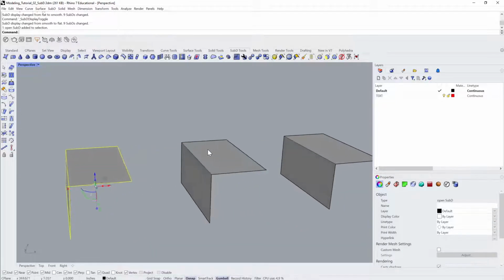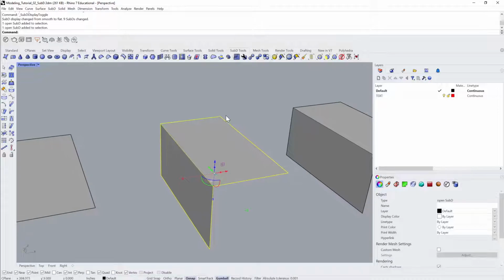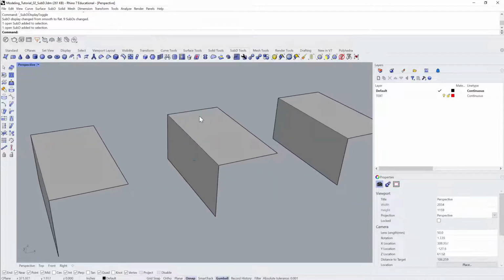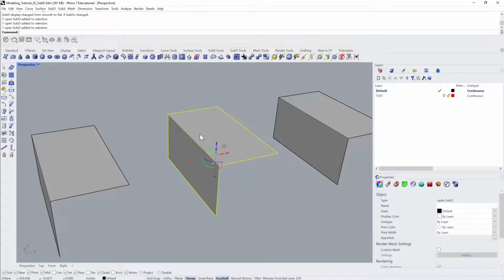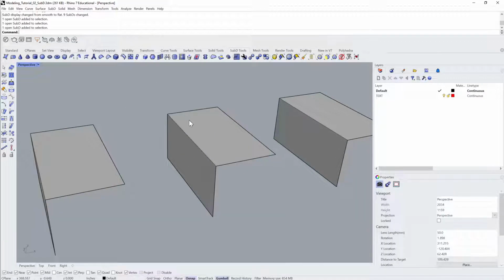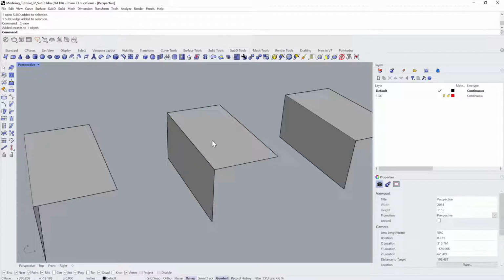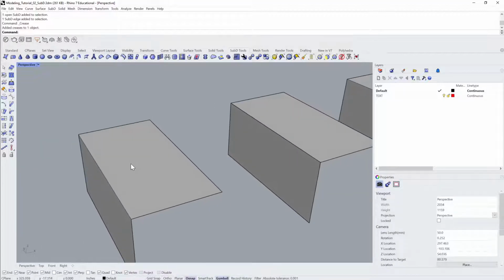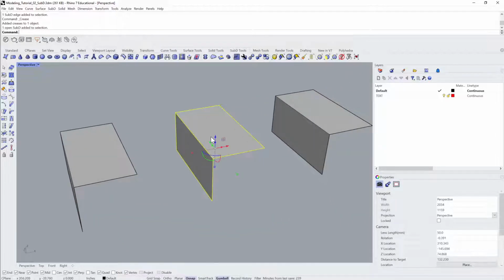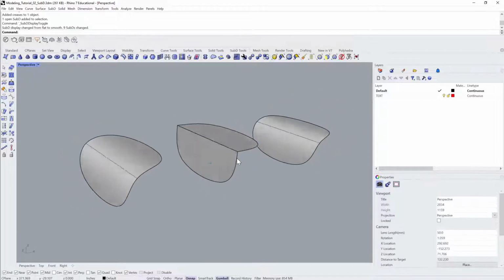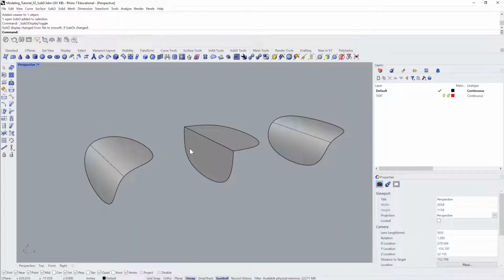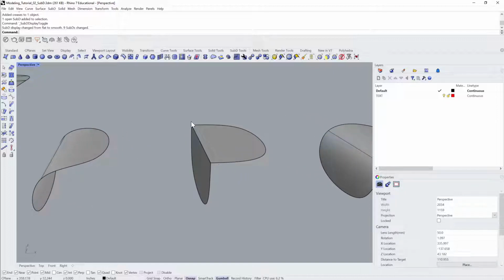and you can see that there's a very rounded transition when I hit the Tab key. Now, if I want there to be a sharper transition here, I can do a couple of things. One is I could add a crease, but then if I add a crease along this edge, so let me just Shift-Control that and add crease. So now hopefully you can see on your screen that we have a light line here and then a darker line here, which is telling us that this edge is creased. And now if I hit the Tab key, you can see that this goes smooth, and now I have a very sharp edge here, right? So that is going to be called the crease command.